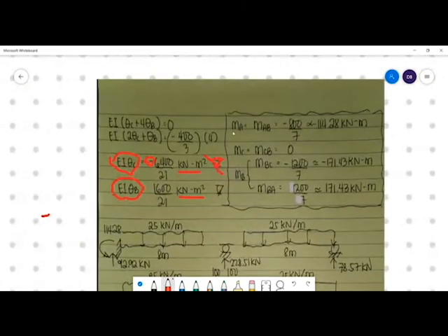Okay, substituting EI theta C and EI theta B, we have M sub AB is equal to negative 800 over 7 or 114.28 kilonewton meter. What we look at here is whether it makes the beam smile or frown at AB. MCB is equal to 0.